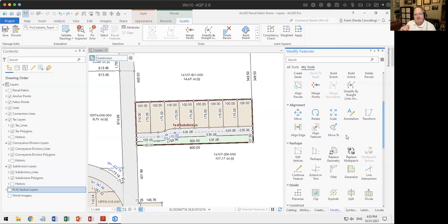Unfortunately, and I think I know where Mark was heading with this, the ArcGIS parcel fabric does not contain that separate vector table that the ArcMap parcel fabric had, where it actually kept track of the movements of the points. You could recall it and say, how much did this point move in the DX, DY? The ArcGIS parcel fabric does not have that complexity right now. So you can't rely upon that. You instead have to do it through standard construction.